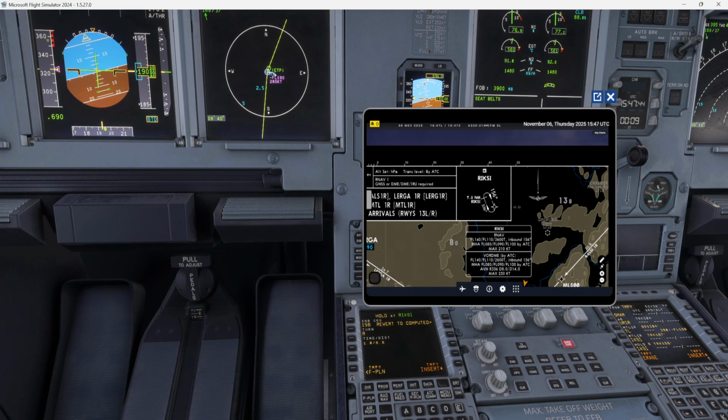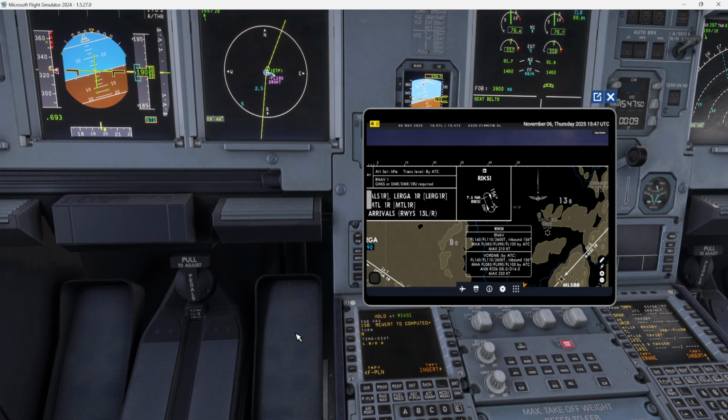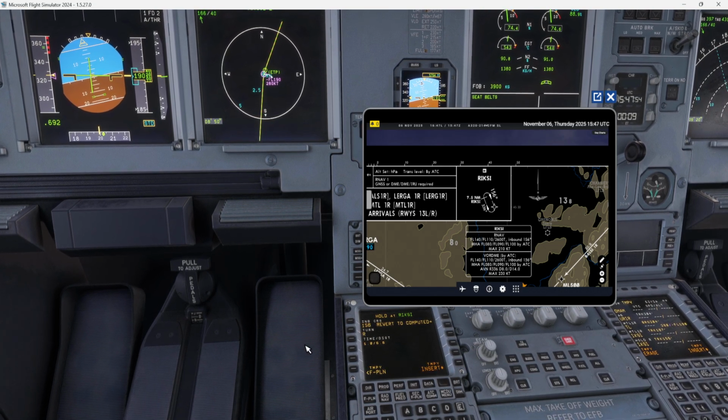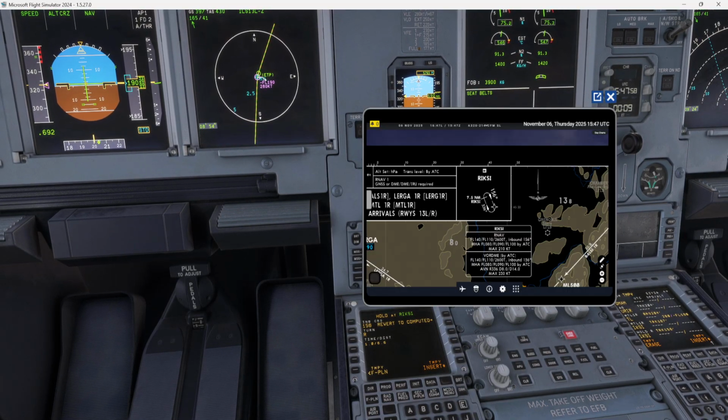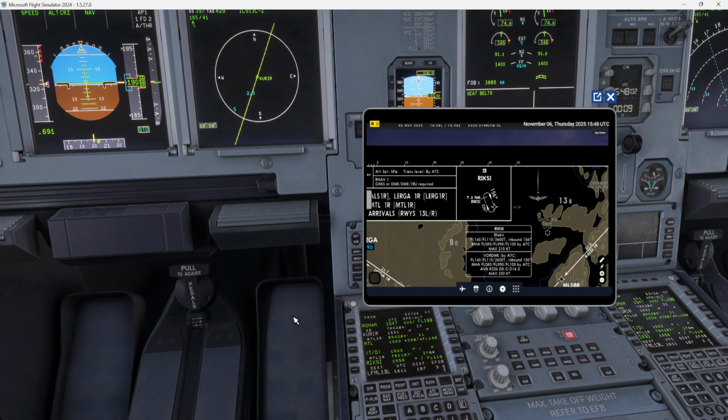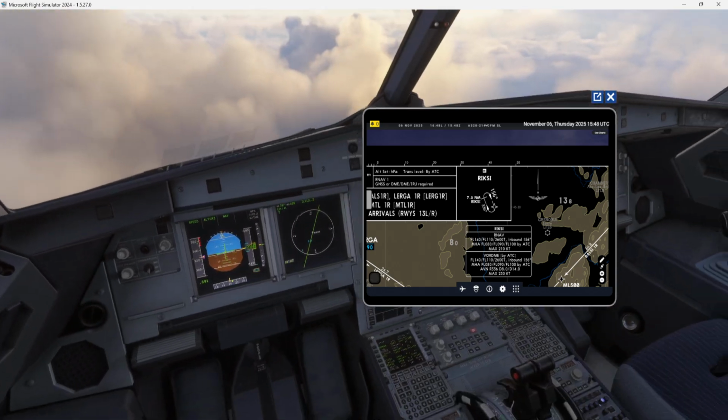Okay, so time, guys. The time here is in minutes. If you are above flight level 140, the hold needs to be 1 minute and a half. But if you are below, the holding time is just 1 minute. This is important, guys.